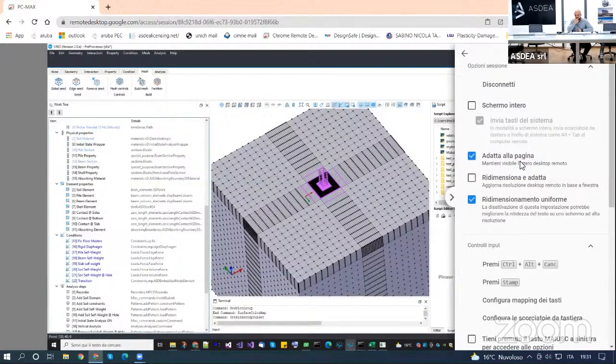Actually, I noticed it today, and I was trying to understand why, because now I need to go and look exactly at the Ricker wavelet. There is an equation to compute the Ricker wavelet for that frequency, but the point is that that is the predominant frequency, it's not the only one, okay? And in fact, if you compute the wavelength from the shear wave velocity divided by the frequency, it turns out that the wavelength was about 70 meters. This was easy to visualize in 2D, but actually it's slightly less.